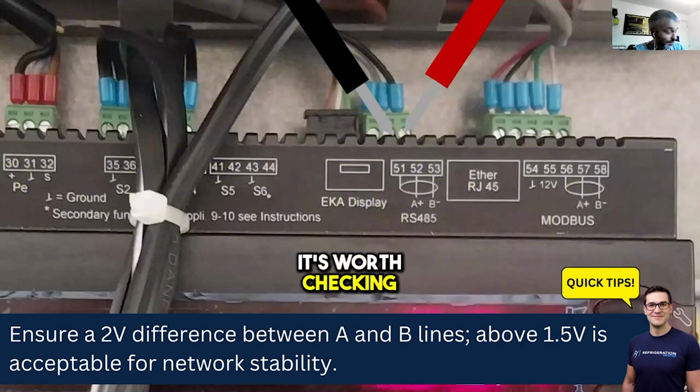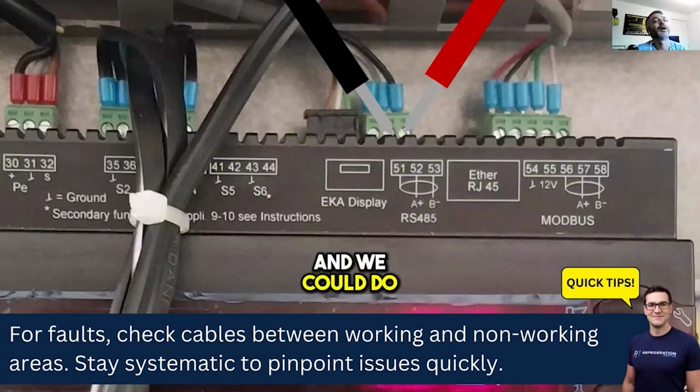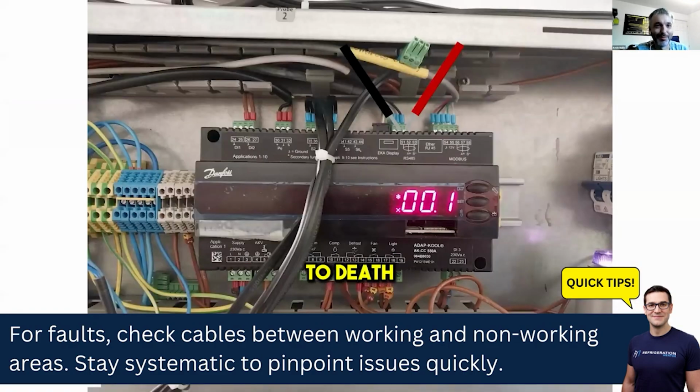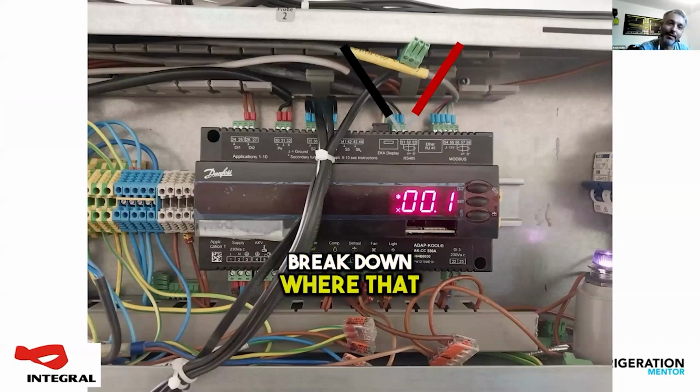It's worth checking. I would say with network fault finding, and we could do hours and bore people to death on network fault finding. Yeah. Network fault finding is all about using logic. If you've got a whole island off and the island next to it's on, the chances are your fault's on the cable between. If you've got one case on an island off, you can sort of break down where that fault is going to be.